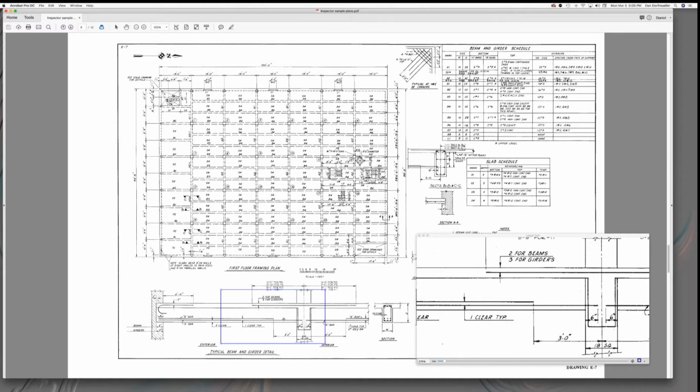And you just think of a 2x4 and you stand on it. You stand on it, it gets lower in the middle, right? Okay, but the edges are still in the same spot from the support. So the stresses come across the bottom, then the tensile stresses come across the top, then they go back across the bottom.